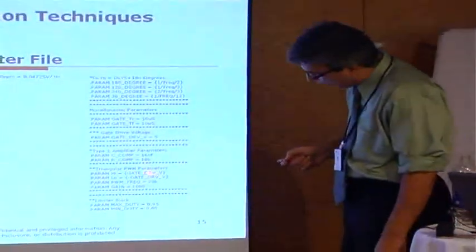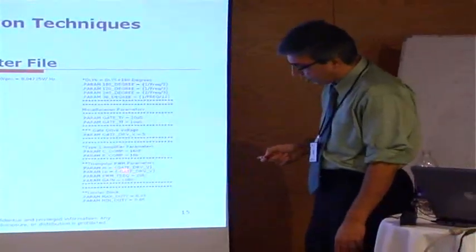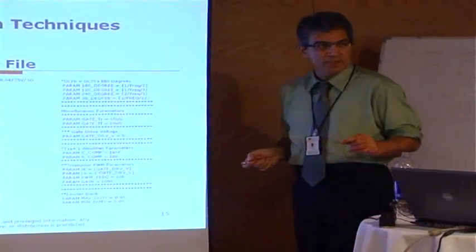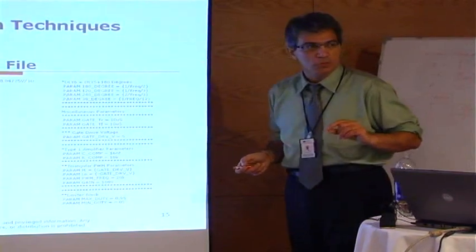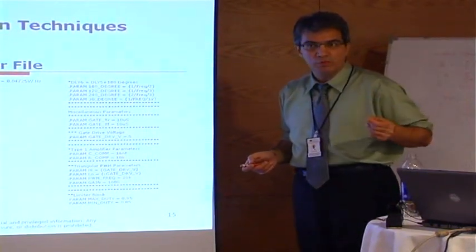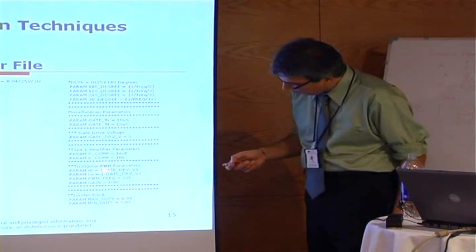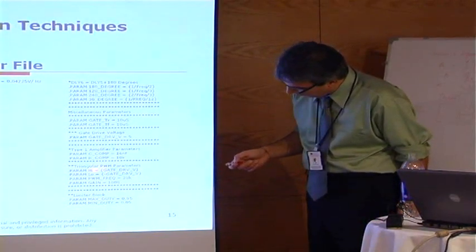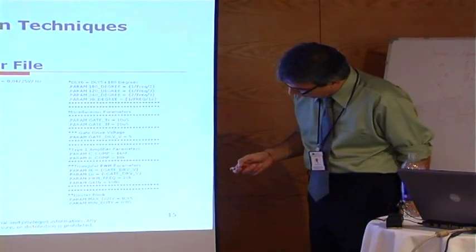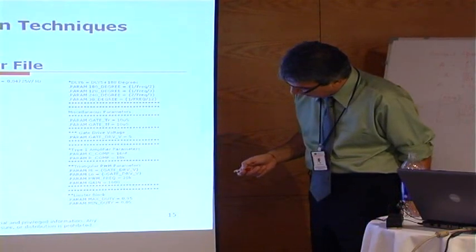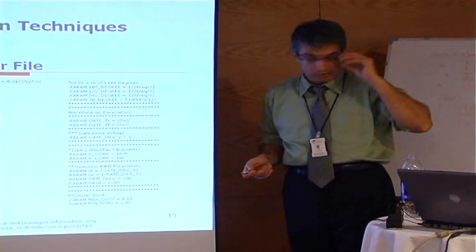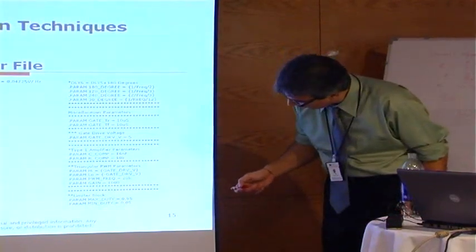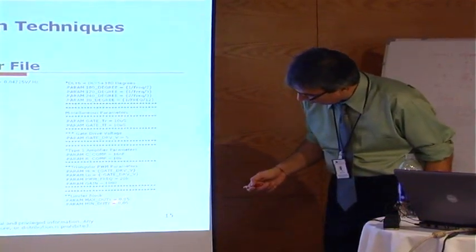And then the PWM parameters. This is a very interesting PWM function, which I like a lot, because it is a whole lot simpler and more robust than what we have used before. For PWM generation, we can set the high and low, and then the PWM frequency and the gain, which helps us with convergence. I'll explain in a minute what the gain means. And then we have the limiter block, 0.95 and 0.05.